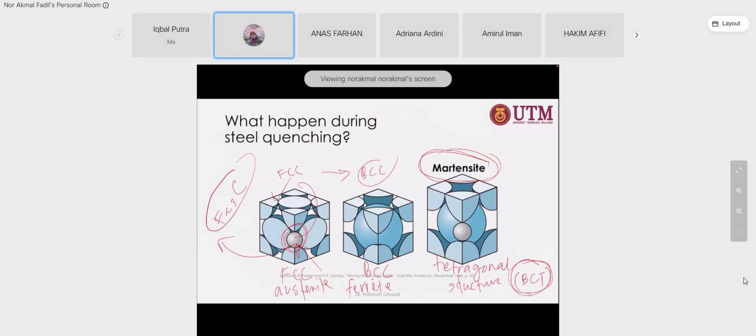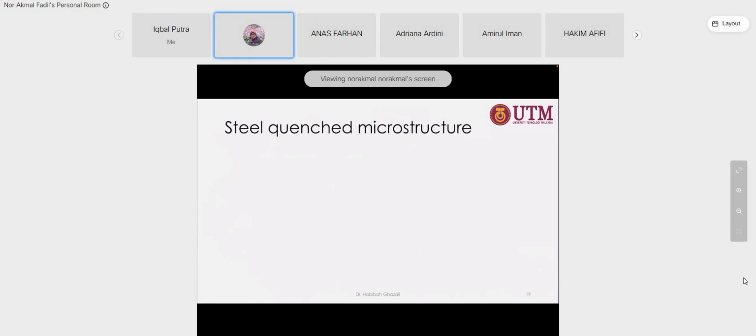Okay, if you want to construct a phase diagram, remember the process to make a phase diagram. It is based on the heat treatment process. It's based on the experimental work where people conduct it at a very slow cooling process, to obtain an equilibrium structure. Okay, this one is non-equilibrium.